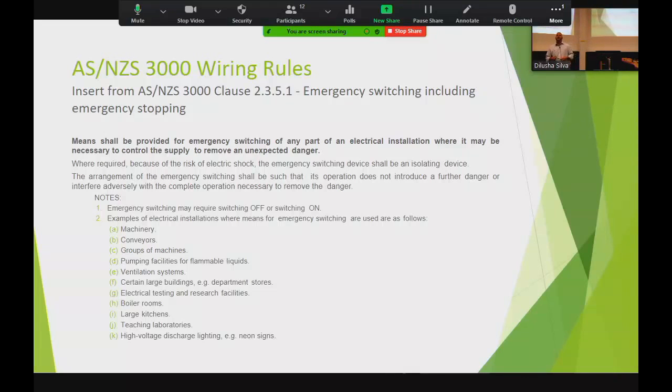In an emergency scenario, when would you want to turn something on? Red light. Okay. Actually, you're not too far off then. We have done labs where when there's been an incident, they hit a button, a red light comes on to advise the tech outside there's a problem inside the space. But another issue you can have is when you have a discharge, so you've got a fume cupboard that's not working properly and gas leaking out, they can hit an emergency button, it kills the power to the fume cupboard, but then turns the ventilation on. So those are the sort of things you've got to think about.